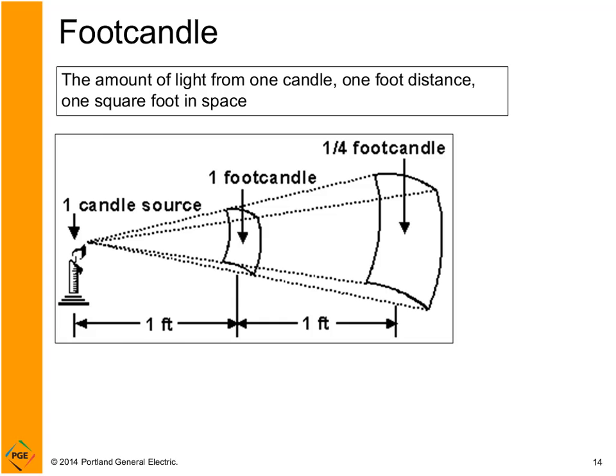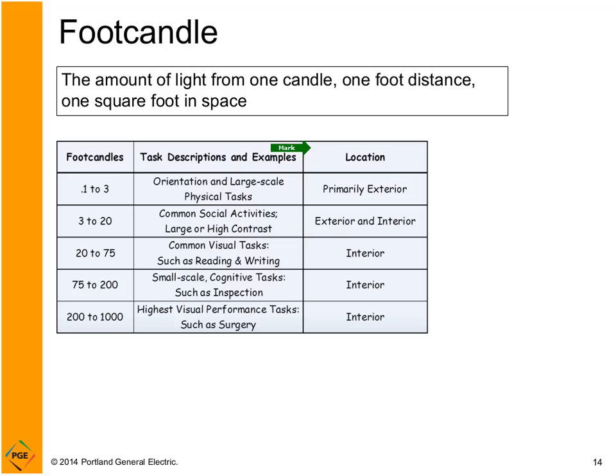One thing before we get to that is it's important to know that distance matters with light. So the same 1 foot candle, if the place that you want to light the work plane is 2 feet away, you don't have a 1/2 foot candle, you're going to have a 1/4 foot candle, because light is affected by the distance squared. So that's very important to know.